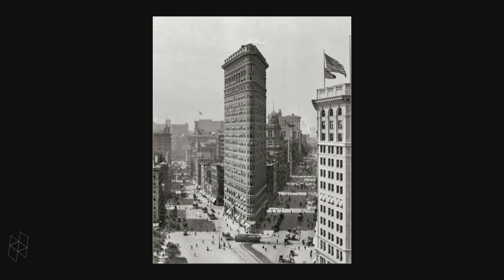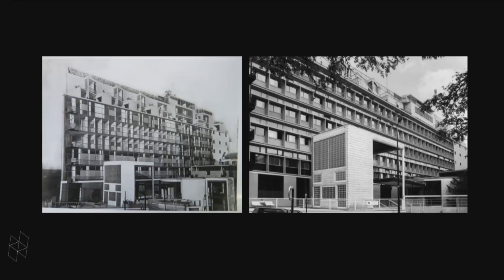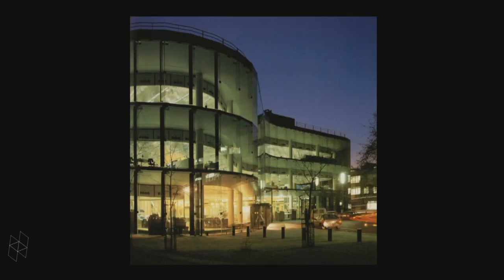The Flatiron Building, at a certain moment, was covered with awnings. This is solar control in a very basic, very straightforward way. Some of these things we've forgotten about when we design buildings. Solar control is such a necessary condition. Le Corbusier also found out the hard way with his Salvation Army building. On the left, the original taut, neutralizing skin, hermetically sealed. On the right, retrofitted with brise-soleil to control the impact of the sun on that west-facing facade. So what are the tools that architects use to control heat gain?